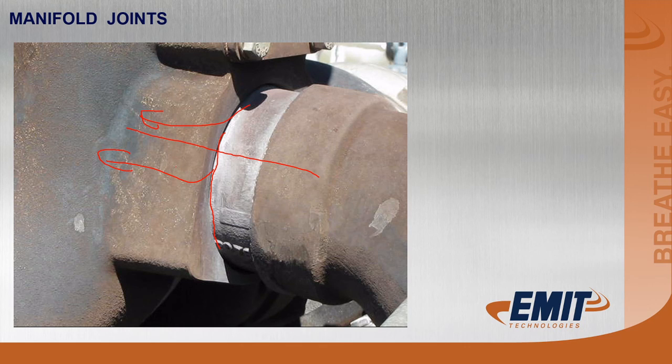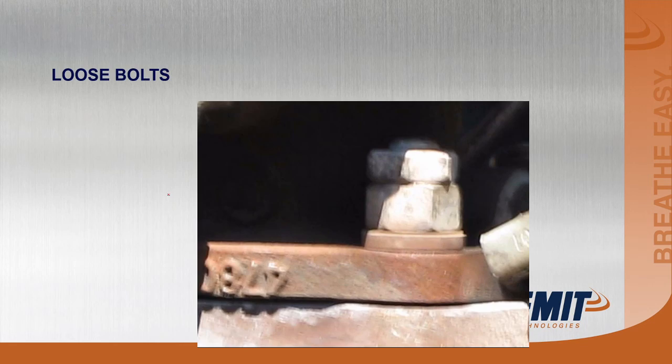Another thing that happens is that oxygen goes across the O2 sensor in this situation. The O2 sensor sees that oxygen and starts to richen the engine up. And in that case, you could easily overtemp the catalyst element.